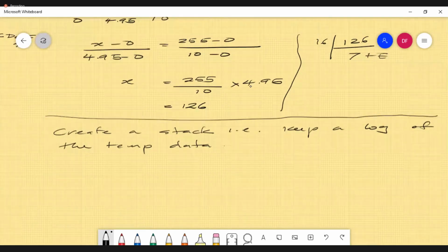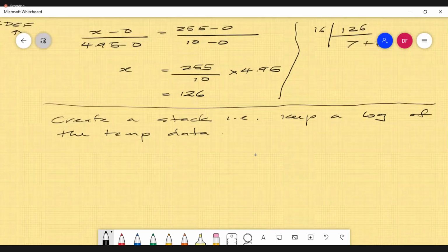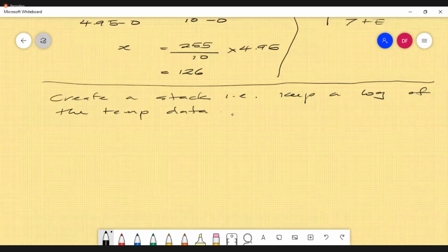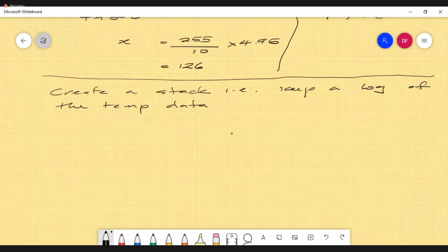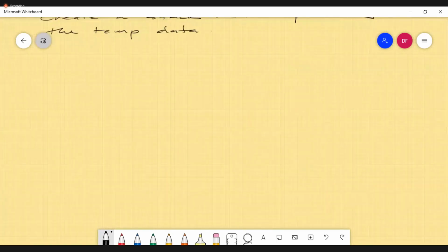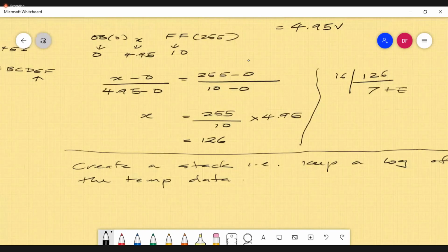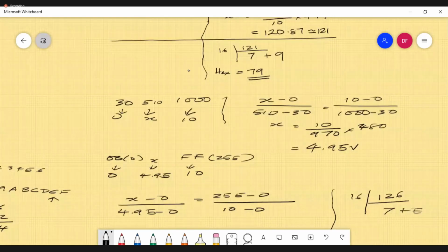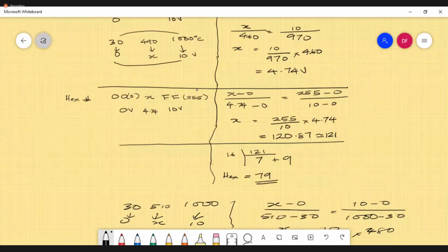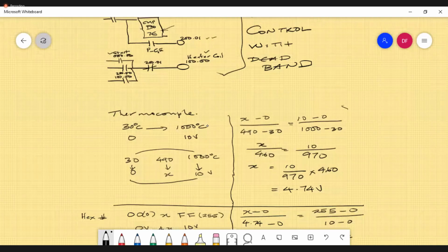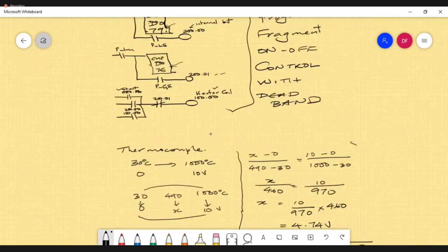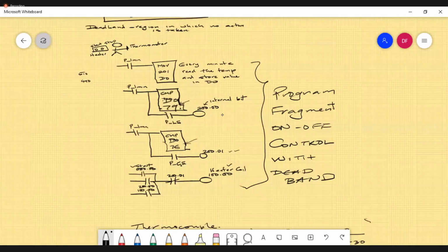All right. So if we go back at it again. Would it be the direct addressing? All right. So we would use indirect addressing. Because what would happen now? Remember, what we did up here is direct addressing, because we put the value into the memory and we say where in the memory we put it. Move the data into D0 is direct addressing.